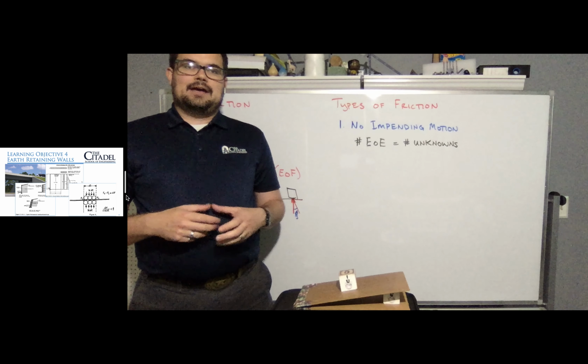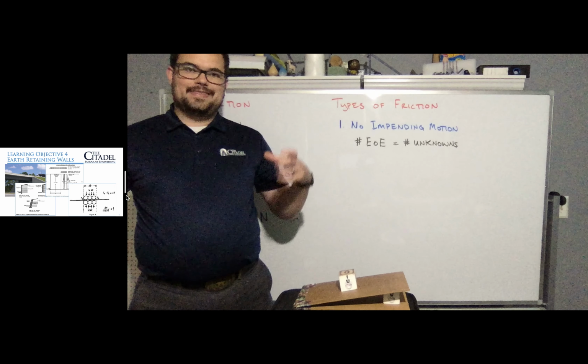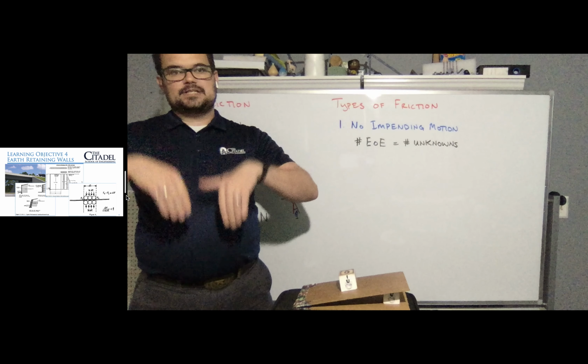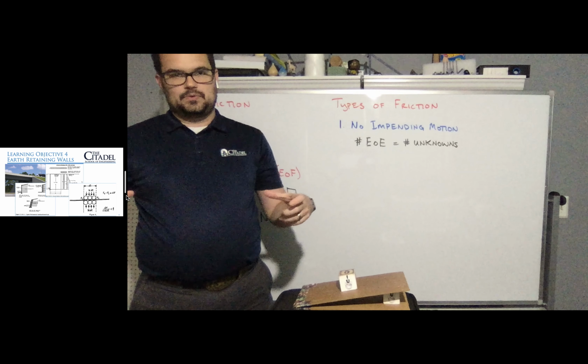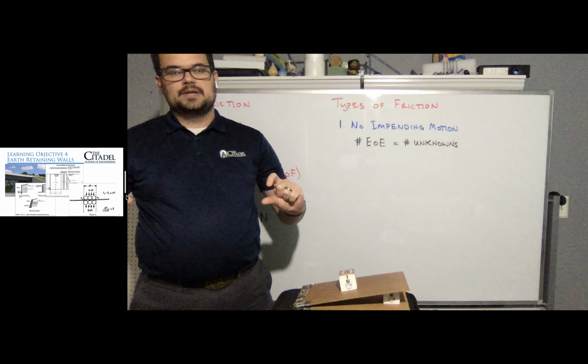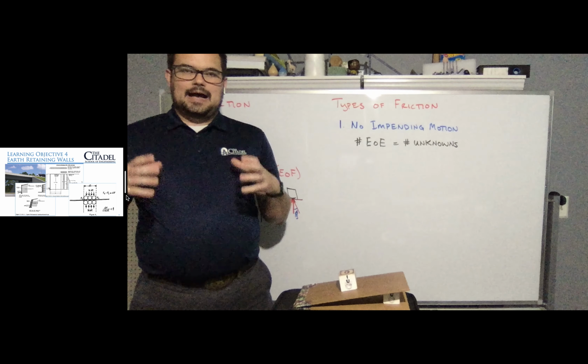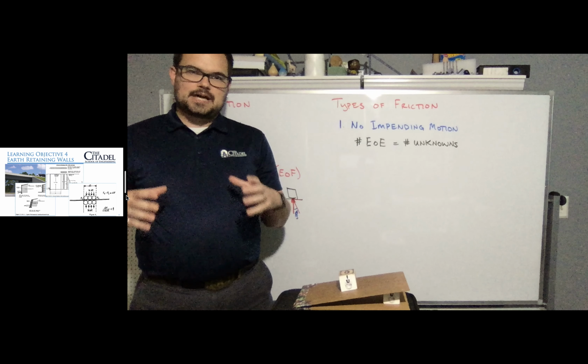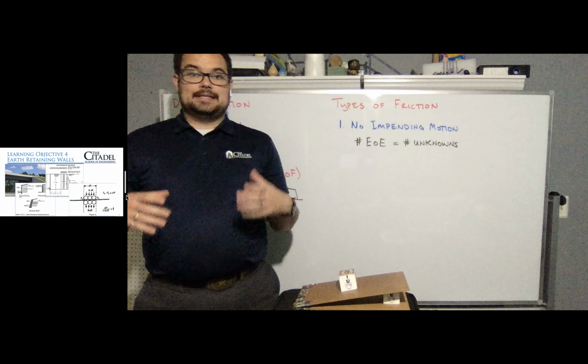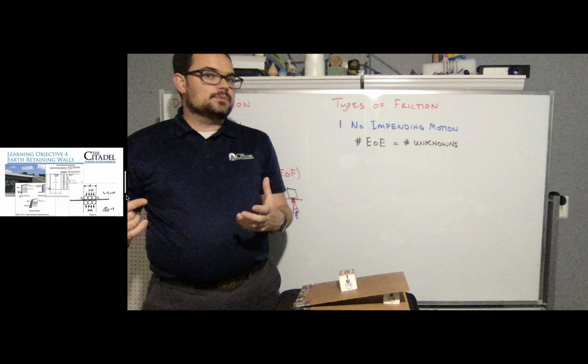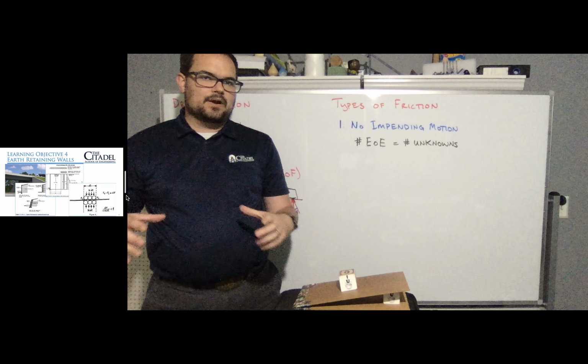And so when you have a wide tire, most of that heat is going to travel through the tread, not through the narrow sidewalls. And so you'll get a sticky, high performance, high coefficient of friction tire. The drawback to that being that you leave bits of tire behind when you drive and when you burn out, and so they'll wear out faster.